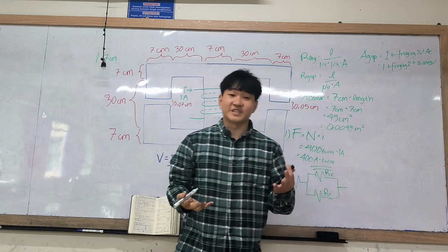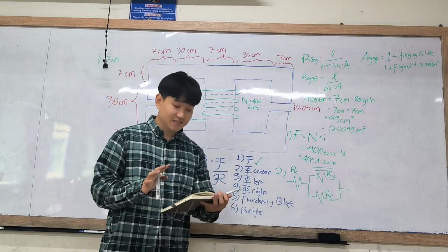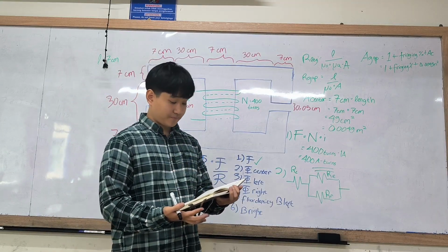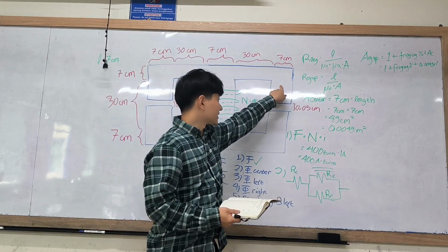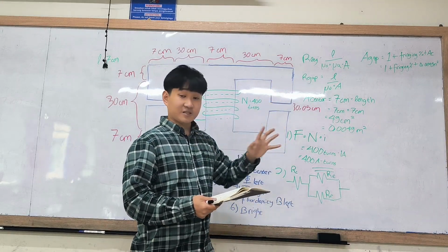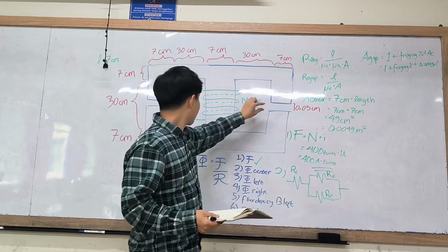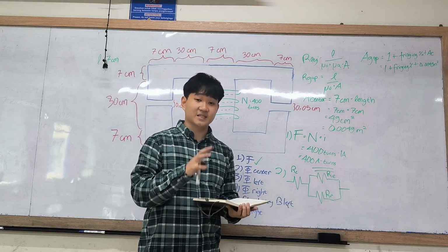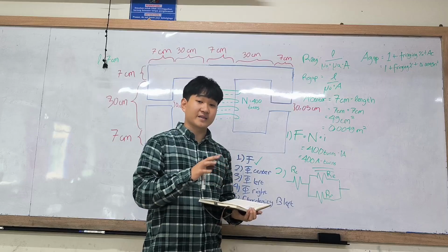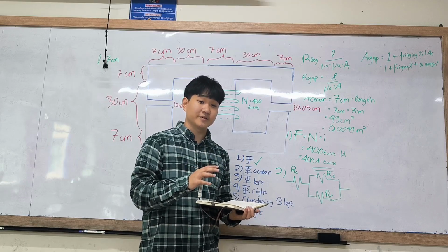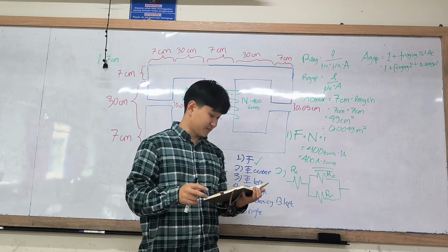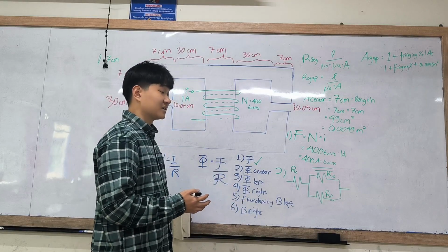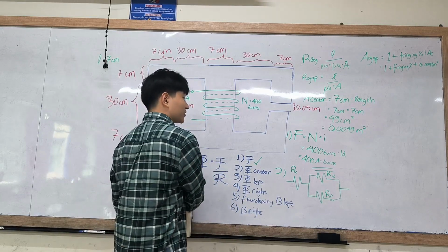But what is this fringing? Fringing is basically the widening of the magnetic flux lines inside this circuit, which is caused by the air gap happening here and here. The result is that the magnetic flux stays the same amount. However, the magnetic field becomes weaker because the area becomes larger, and it also inadvertently decreases the level of magnetomotive force.